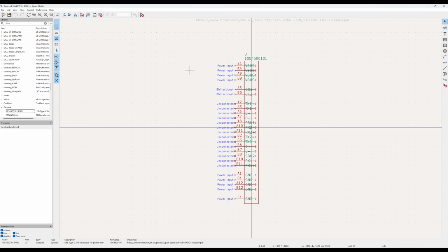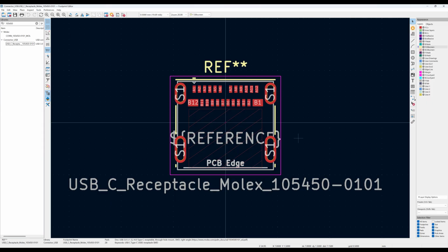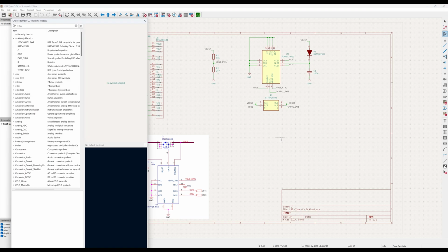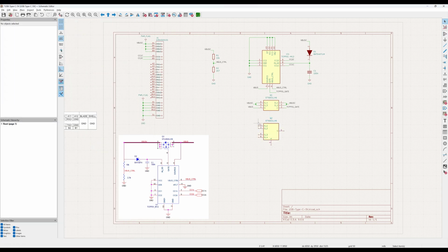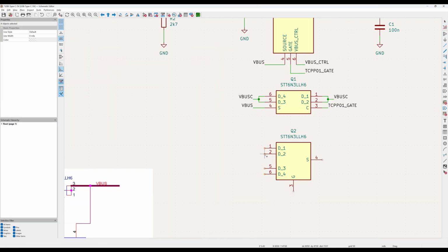The S1 pin, connected to the connector's shield, is included. Lastly, the footprint from Molex, using UltraLibrarian, which did not connect the shield to ground, is replaced with a built-in footprint that does. Let's now insert custom symbols for IC1 and Q1 and rewire the schematic.